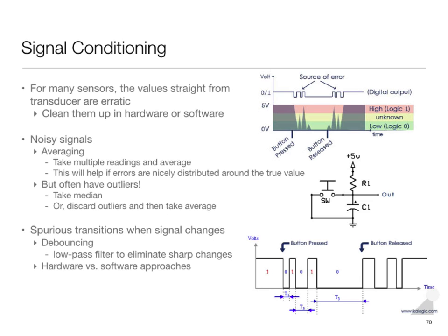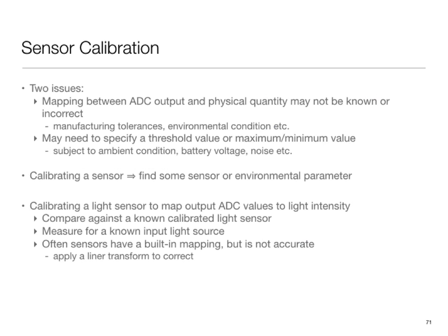There are these kinds of issues which sensors just suffer from. These button-type sensors are quite common in security systems also. They might have in the door hinge some sort of a thing which just presses, but again the signal would not necessarily be clean at the lowest level, so you want to clean them up. So signal conditioning is the very first thing that one has to do.